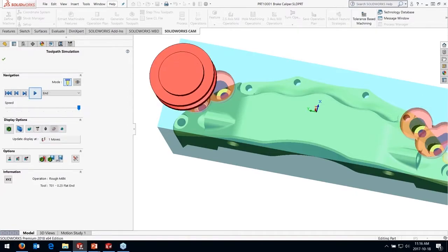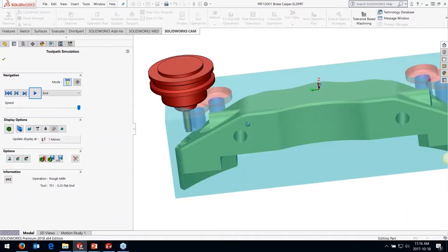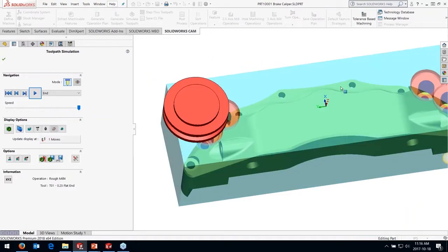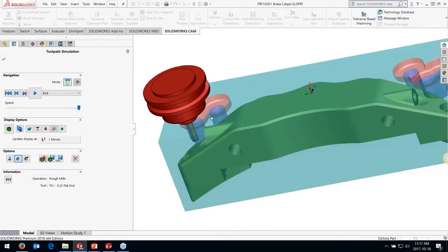The ability to save those settings to a database means I can just go, hey, I've got a strategy built for this. It's going to go and do that work for me. It's going to register all the cylinder diameters, profiles, and everything else, the start positions, depths. If they change from model to model, it will actually update these values as well. So it's not just that it has to be this shape every single time. So I've got a cylinder bore strategy that I've just been in and customized here.